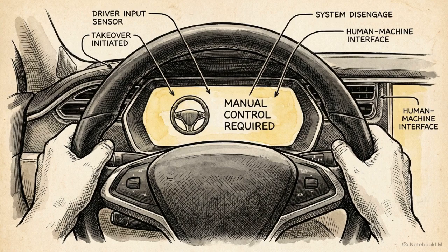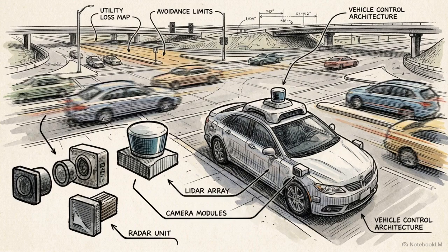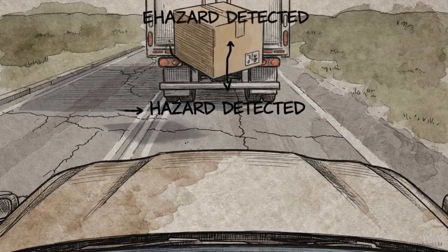By removing the autonomous system from the scenario, the hazard is avoided. However, relying solely on avoidance can be counterproductive. If you avoid every complex scenario, the vehicle loses its ability to perform its intended function in the real world. This is where mitigation becomes essential.